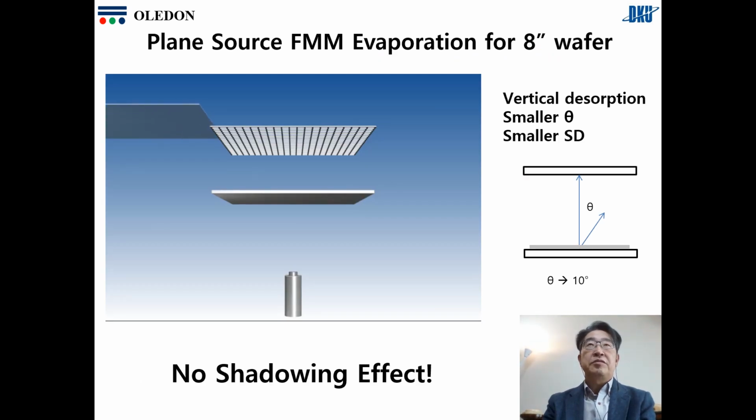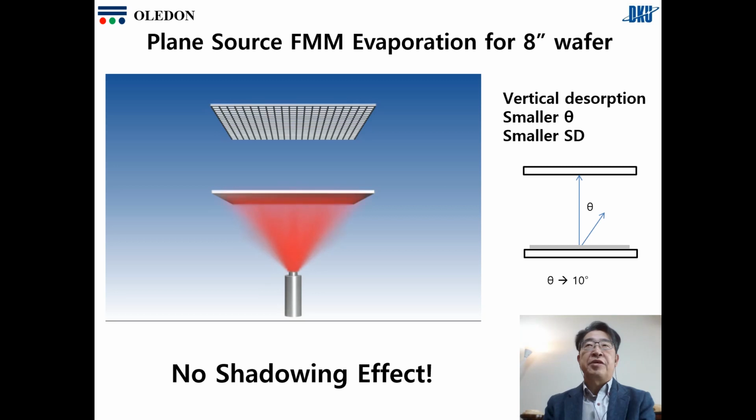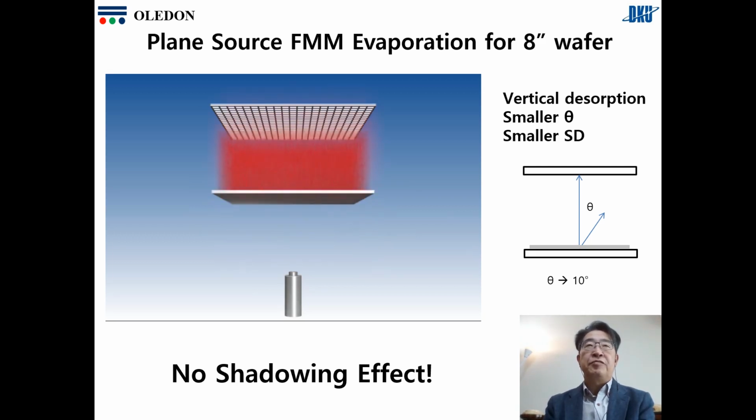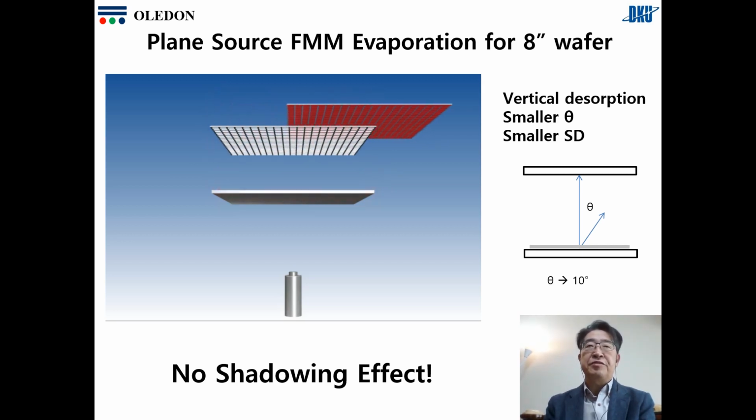The CMOS substrate moves into the chamber to be aligned with the fine metal mask. The organic molecules are evaporated to deposit on the metal plate as a donor film, which will be rotated to re-evaporate. The donor film molecules are vertically dissolving to provide a patterned target film on the CMOS substrate, to be taken out of the chamber.